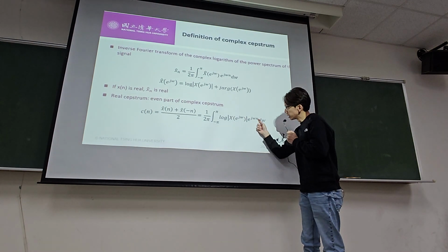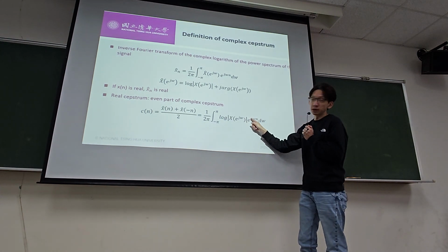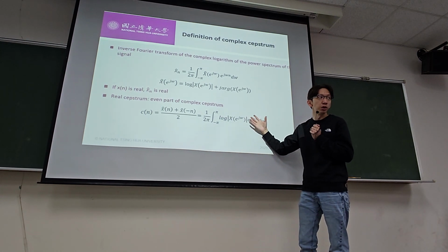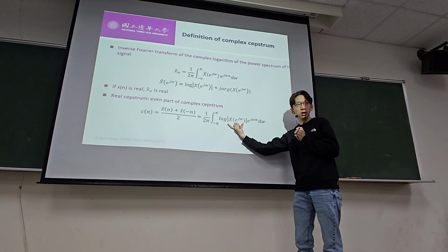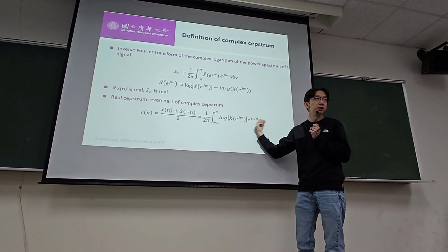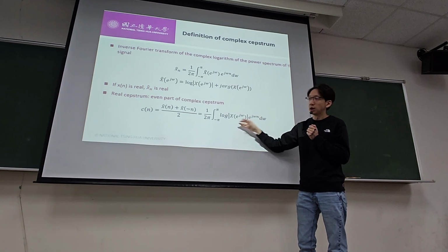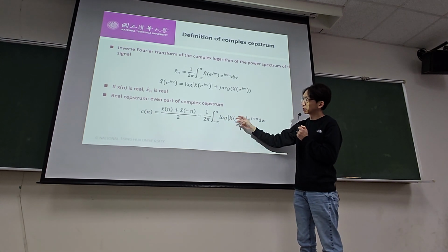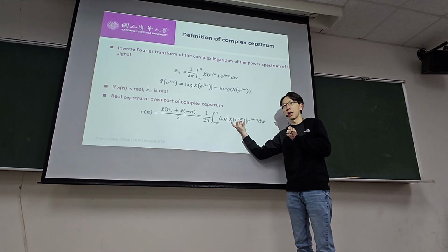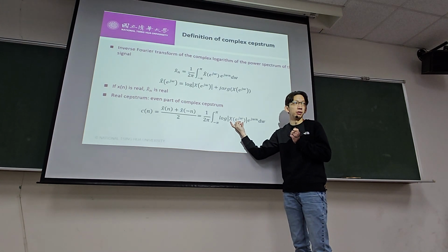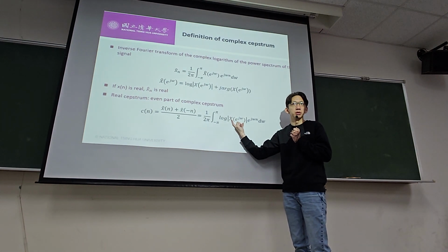Like I said, the inverse Fourier transform is the only thing that's different here, right? There's a minus sign in this case. So what you effectively do is still take the log of the spectrum and do another Fourier transform. That's basically what the cepstrum is doing. This particular process, taking a log, makes things that are multiplicative become additive.